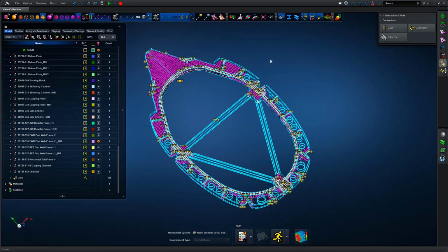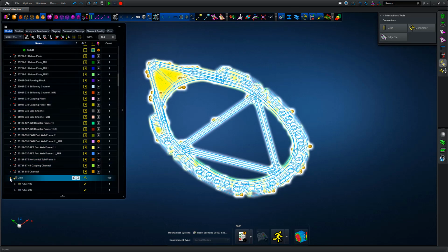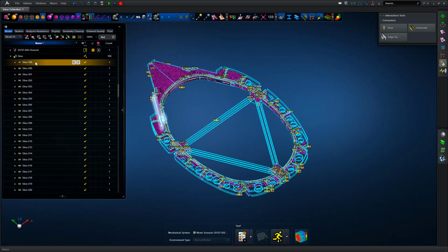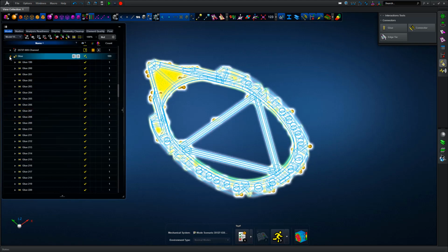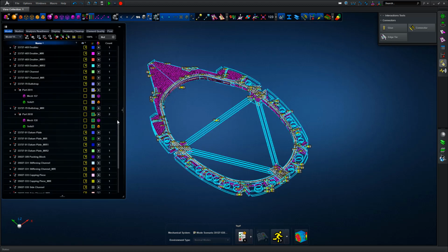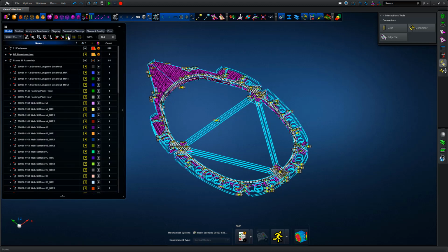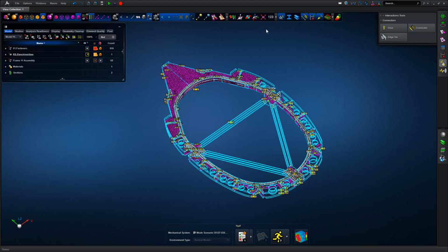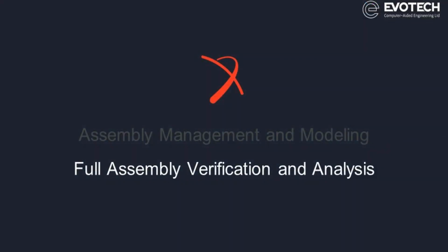So once we've got those controlled, we can view each glue pair, so a connection between two parts or sub-assemblies, and cycle away through the definition within the model browser tree. One thing I'd say is that the glue technology does consider the extreme fibre surfaces of each shell element. So if you've got two solids butting which are represented as shells, it will glue them together correctly.